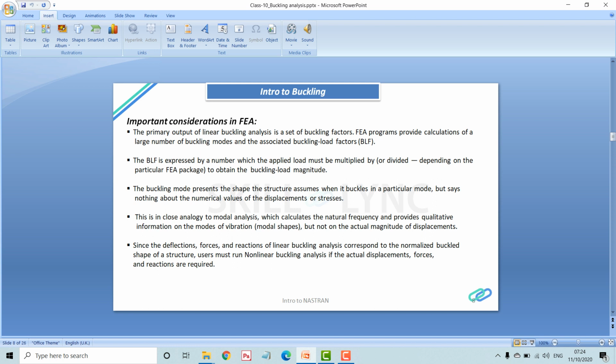So the buckling mode represents the shape of the structure that is undergoing the buckling, that is, whatever we have discussed now, when it undergoes a wave pattern or an alternating pattern. Those are buckling modes. The user might extract different buckling modes based on the requirement. You might go for the first five buckling modes or the first 10 buckling modes, based on whatever the requirement is, or the goal to which they are designing the structure.